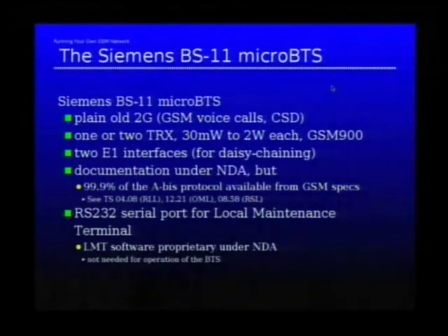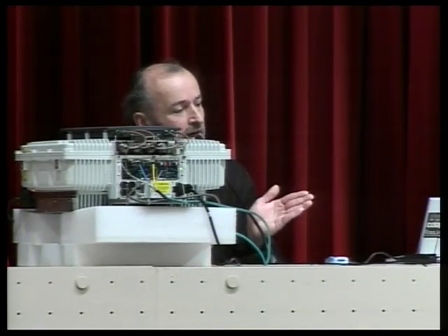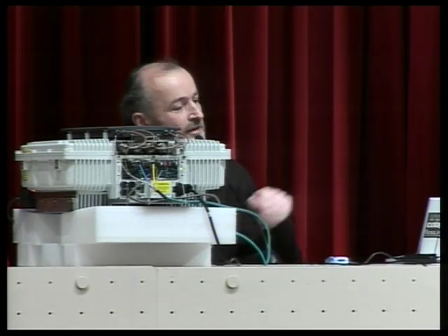The interesting thing for the base station transceiver is that you can set up the power which it uses on the output. There are 4 stages between 13 milliwatt and 2 watt, and you can choose which stage it uses. So even if you should not try it at home, if you try it, turn it down to 30 milliwatt, then probably you don't disturb too many people. You should not use the 2 watt because this is the power similar to your phone, so you will have a really huge range. The antenna is a directional antenna, so you usually have roughly 180-degree transmission direction. But anyway, I would suggest if you try it, even if Harald says, okay, don't try it, then turn it down to 13 milliwatts.